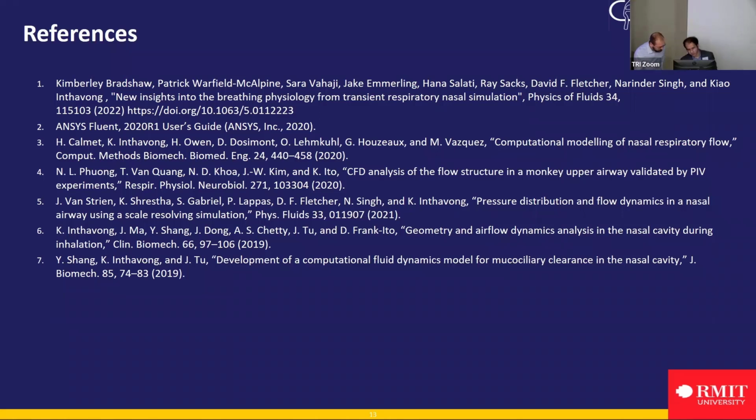The second question is, what was the time step and the mesh size? Okay, so the time step was mentioned before. It was 0.0025 seconds. That was to maintain a Courant number less than 1 for stability. The mesh size wasn't overly huge. I don't have the number off the top of my head, but it was much less than an LES simulation due to the very low Reynolds number that we're using through the anatomy and the fact that the LES is only being used in that bulk fluid region. Again, if you want to email me, I can send you the exact mesh specifications.